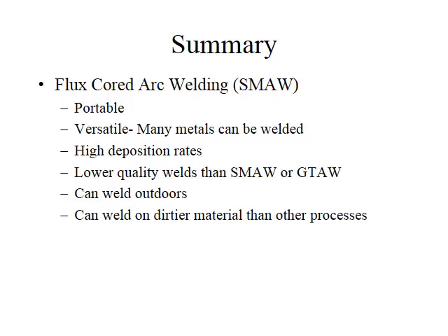The equipment is essentially the same for externally shielded flux-core arc welding as is required for the gas metal arc welding process. For self-shielded flux-core arc welding, the equipment is the same, except that no bottles, lines, switches, or nozzles are required to provide a shielding gas.